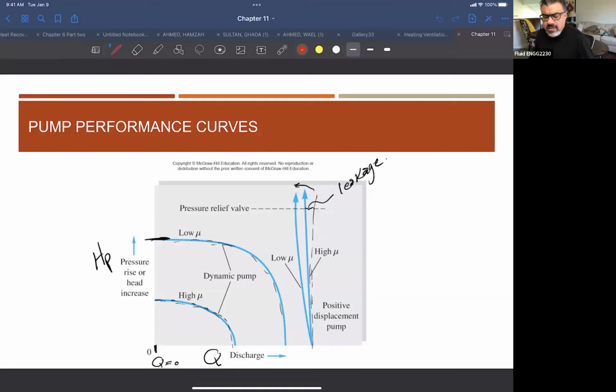So the pressure at the exit of the pump depends on the losses in the line, on how much the pump is resisting. For a positive displacement pump, the pump has to operate and the fluid has to go outside of this pump no matter what, right? For the hydrodynamic pump, we said there might be a possibility of having the valve at the exit side of the pump completely closed, right? And you still see the pump is running, the impeller or the rotor inside the pump is running, while the pressure increases to a certain limit, and that's it.